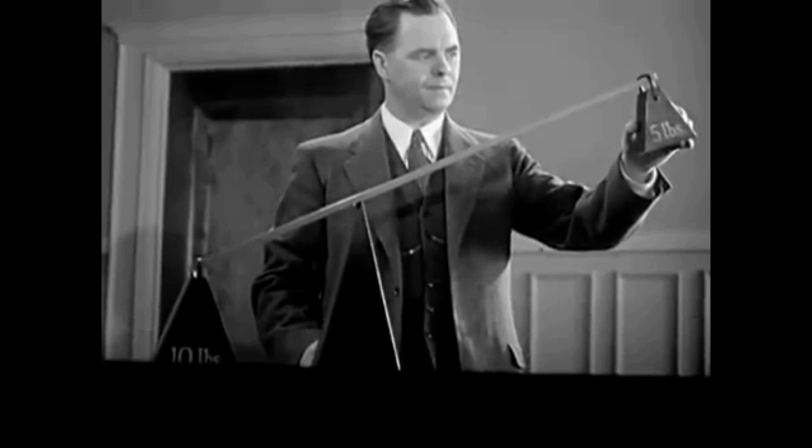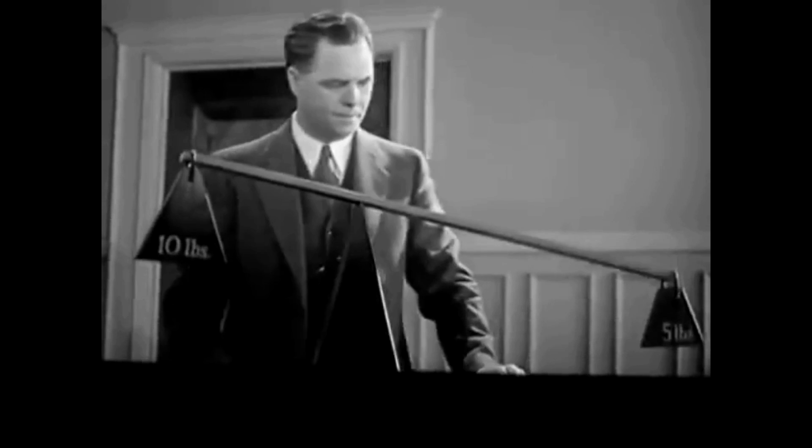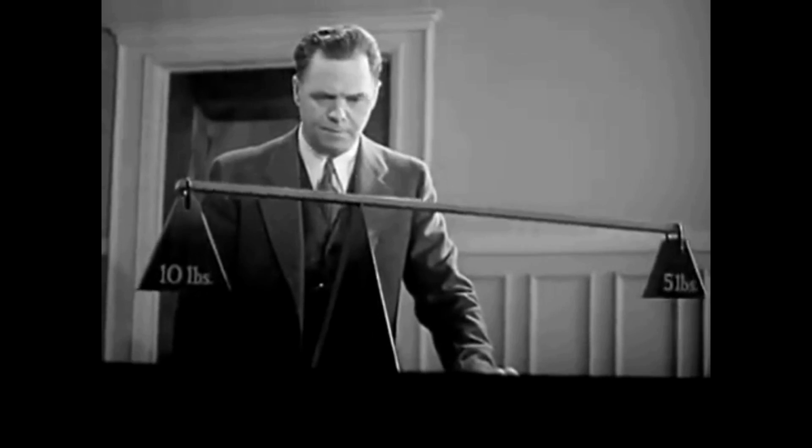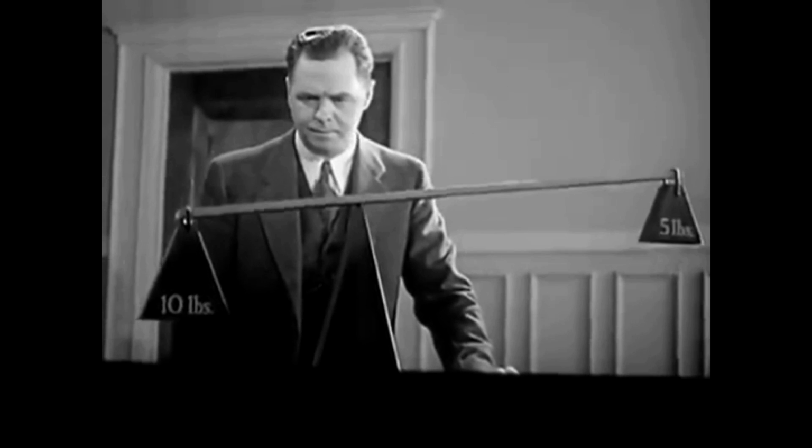from the fulcrum. A 10-pound weight can be balanced with a 5-pound weight, but notice when this is done, the 10-pound weight moves half the distance of the 5-pound weight. If we were to change the shape of the lever, where the fulcrum is now a shaft, we have a crank. We can add another lever to make a double crank.